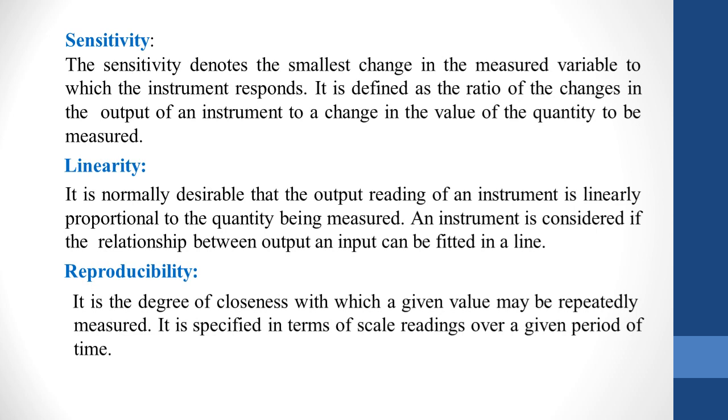If, for an instrument, the calibration curve is not a straight line, it should not be concluded that the instrument is inaccurate. We can't say this; it is a misconception. A nonlinear behavior does not essentially lead to inaccuracy. Such an instrument may be highly accurate as ever.